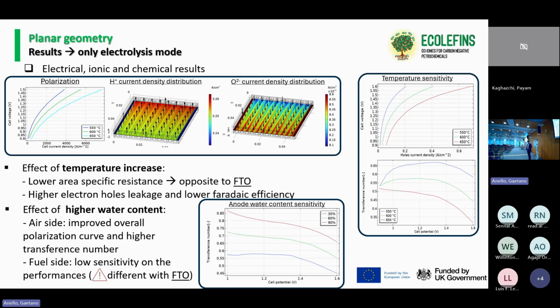So we can perform sensitivity analysis in terms of temperature. Higher temperature obviously will improve the electrochemical performance and hydrogen production, which can be opposite to the Fischer-Tropsch, so we will have to find a trade-off. The goal of the project is to reach good performances around 400 degrees Celsius. For now, we usually work at 500 to 600 in the typical reactor, so there is a big gap from the project.